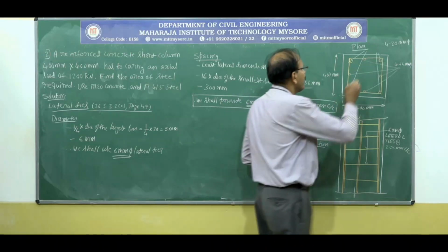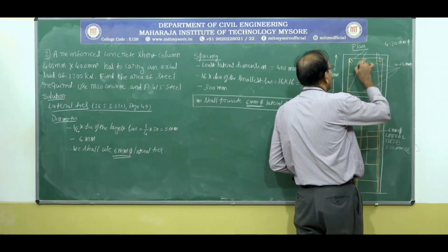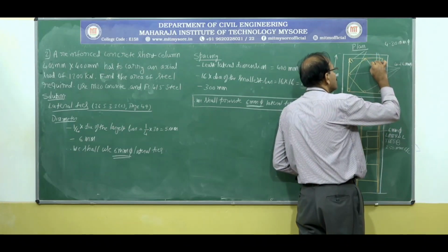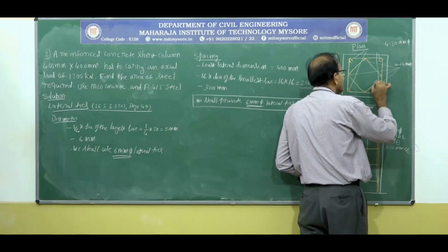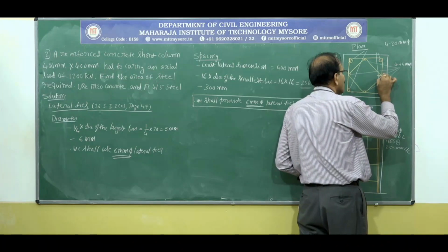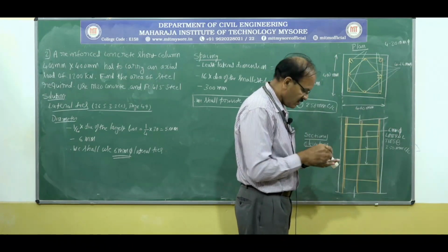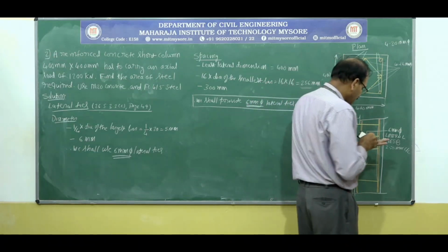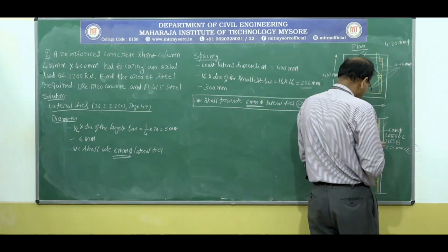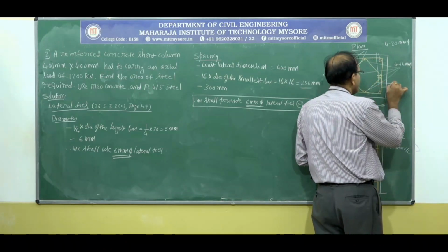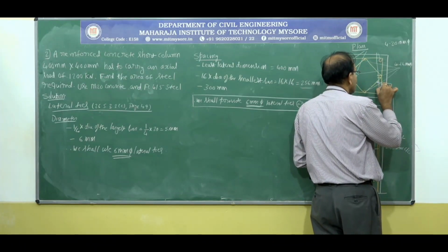And of course we are providing one more set of lateral ties, which is recommended, again at a spacing of 250 millimeter center to center, that is this one and this one.